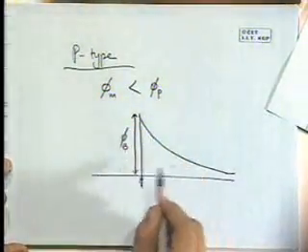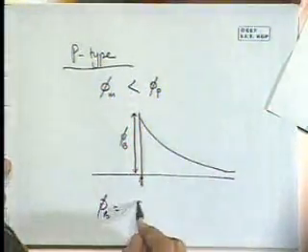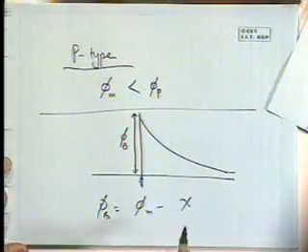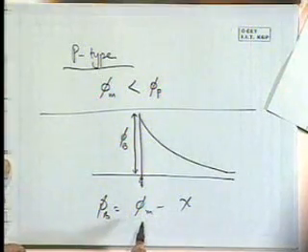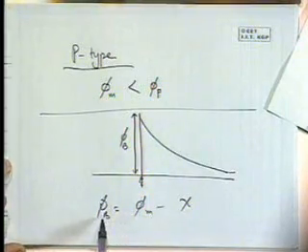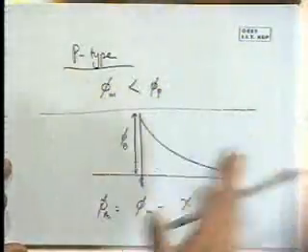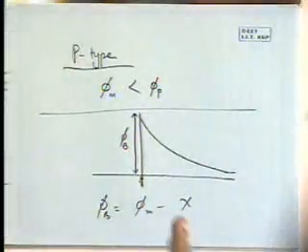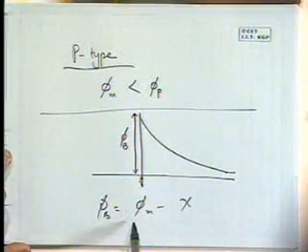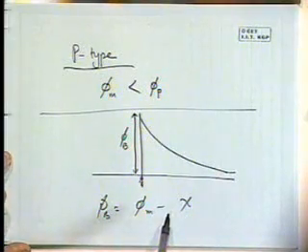Now, one would presume that phi b is equal to, in the case of n-type, phi m minus chi. So, for the same semiconductor, if I use a different metal, which has a different metal work function, one would suppose that phi b changes. And phi b is something that we can measure experimentally from a current voltage curve and things like that. So, if I measure phi b and plot it versus phi m, I should expect a straight line for the same semiconductor. The reality is that sometimes that is not the case.